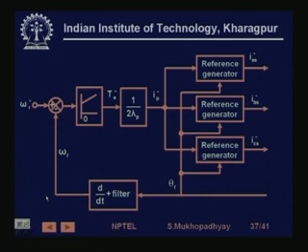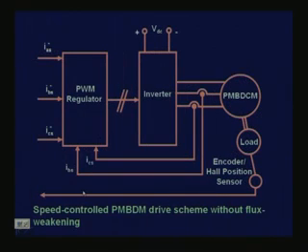So this is exactly the same thing that we are taking. This is just a speed control loop. So the speed reference is there, real speed, then PI control, then this is a proportionality controller, and then you generate the current references, and then this current reference will go to a PWM regulator which will create the switching, not only to have the current at a certain level, but also to have the sense of switching such that the MMFs rotate in the proper direction.